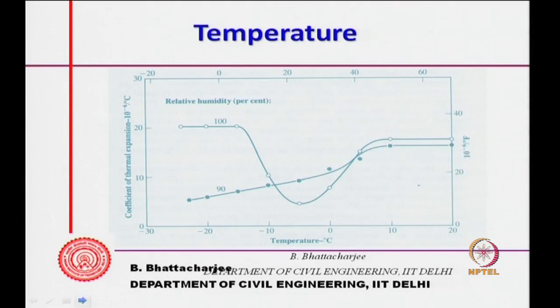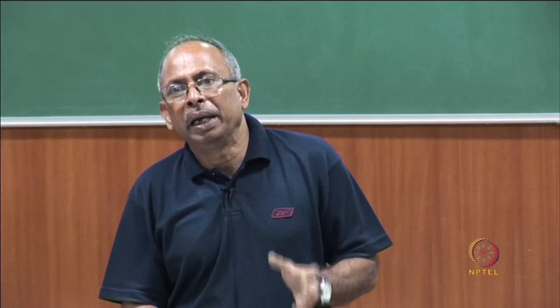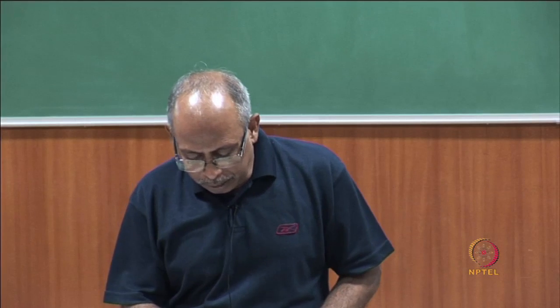It is also dependent on temperature. There are some observed experimental results. At relative humidity 100%, the coefficient of expansion is something of this kind, and it depends upon temperature, at low temperature like -20. Here, water will be more or less mobile, although the properties of gel water are different. It is not the same as free water; it will not be like free water getting frozen. It may not get frozen at all, but the properties are different.